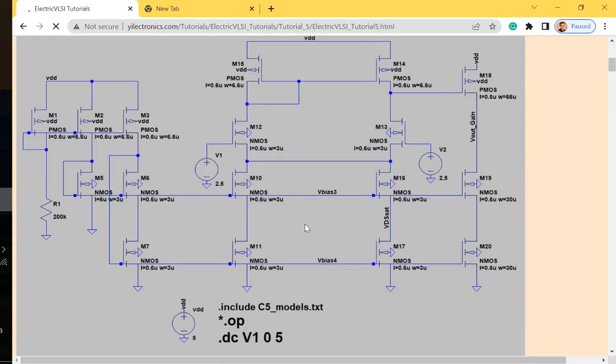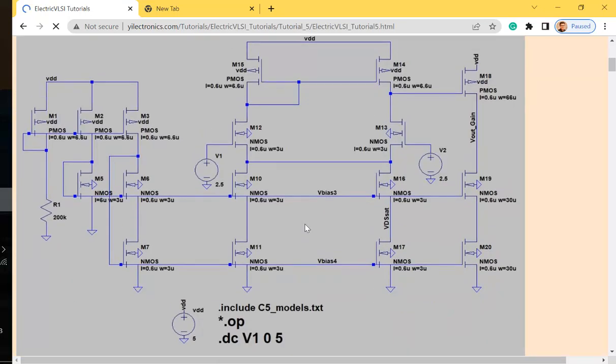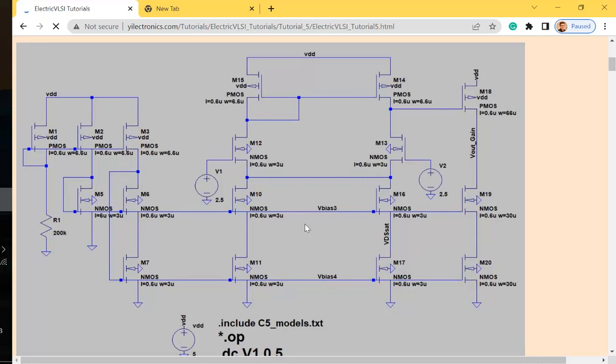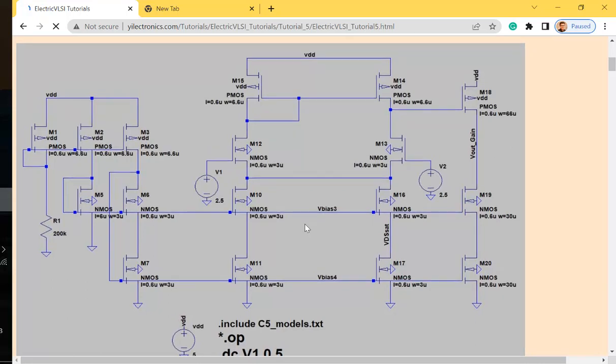There's something like this: this is the op-amp, and this is not the only version of the op-amp in the world, right? It's just the CMOS version of it. You can build it using BJTs, but this is a CMOS version. The PMOS and NMOS form a differential pair.